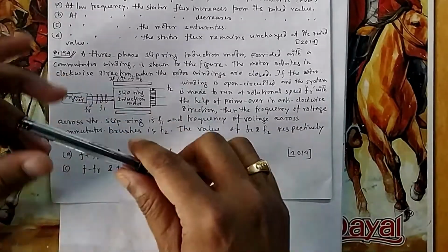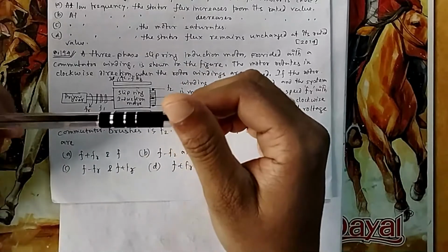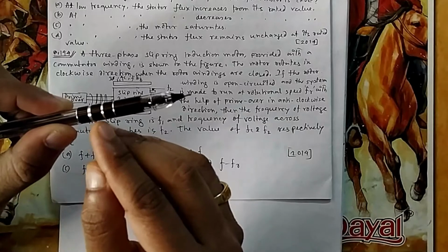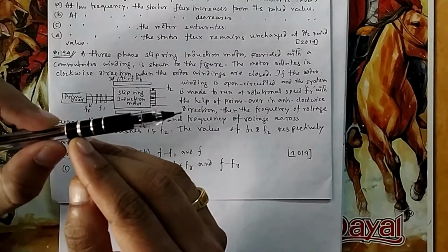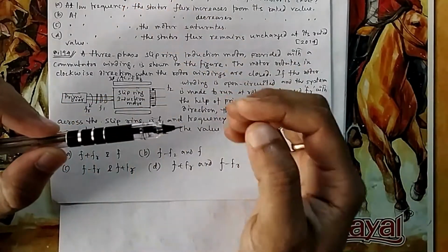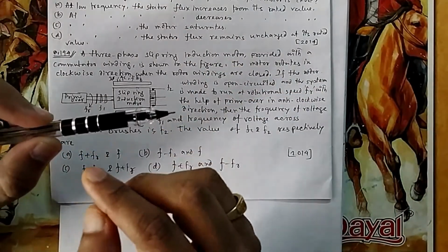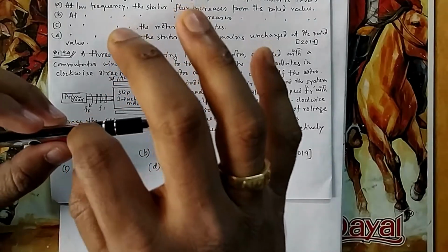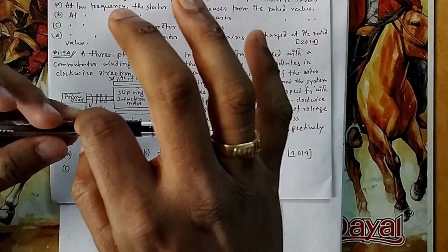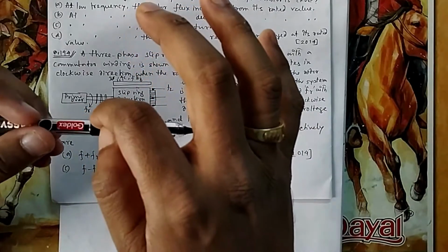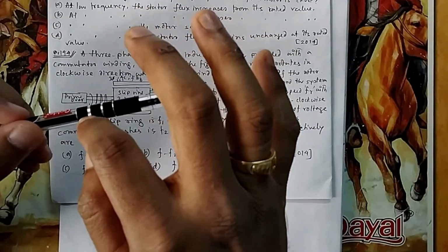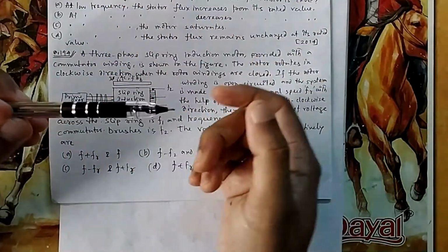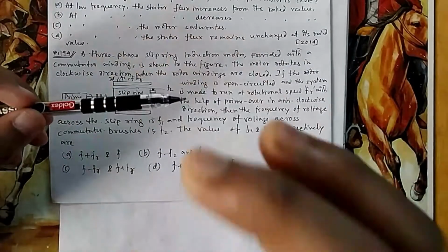Suppose this is my rotor rotating, then you can see these black shades, this one and this one, or you can see these white strips, 1, 2, 3. So this is the slip ring. One winding will be connected to this slip ring, another winding will be connected to this one, another winding to that. Whatever the voltage of that winding, one terminal will be put on this one. So whenever it rotates, the same winding will be connected with that terminal. Suppose I take the R terminal, so the R terminal is connected every time with that R winding. What happens in the R winding, that will come.